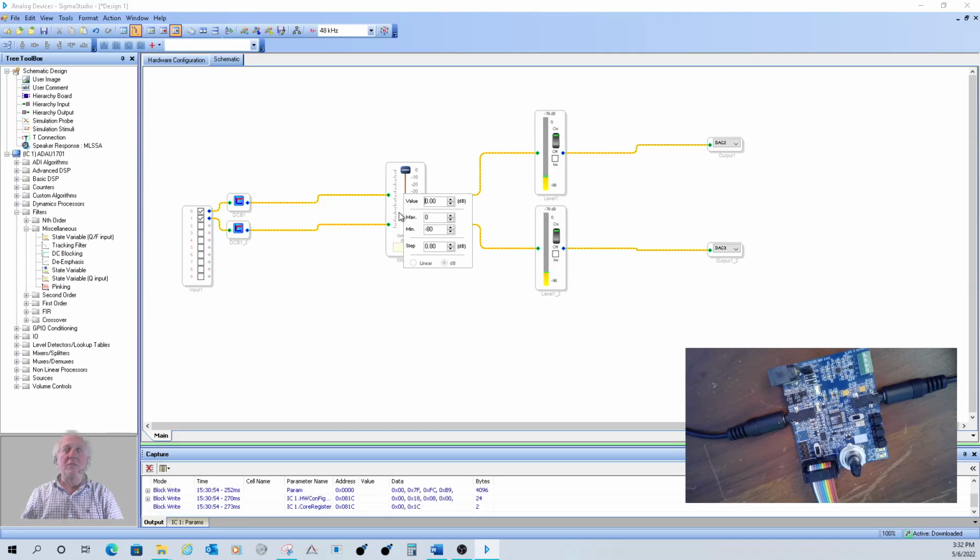Seems odd to go over 0 dB, but in the DSP, 0 dB FS, we're generally talking about the serial ports into and out of the core being 0 dB FS at 24-bit, and then in the core, we're still calling it 0 dB FS, although technically it's not. But you need to get back to that reference level, so it's good to call it that and know that you have gain above it, headroom above it. So anyhow, pretty cool. We're pretty far along on my basic project, by the way, and what I want to do.